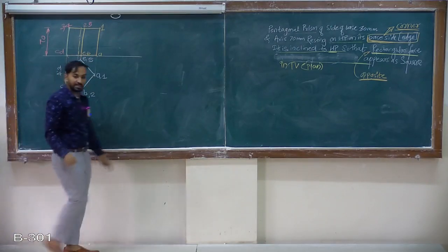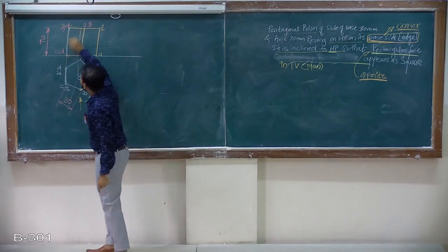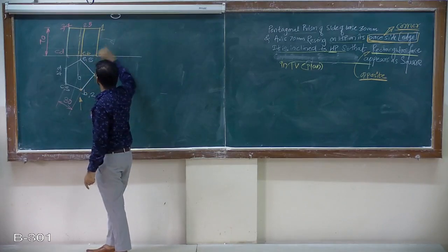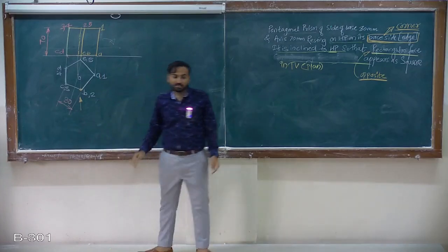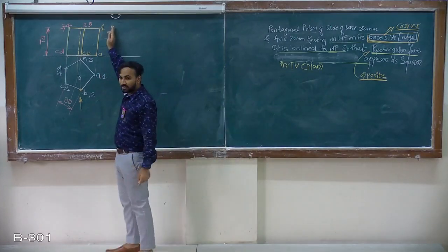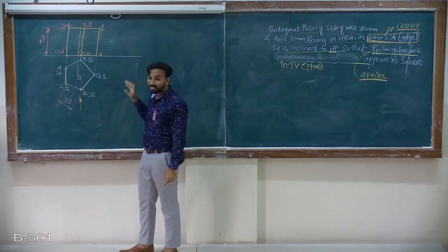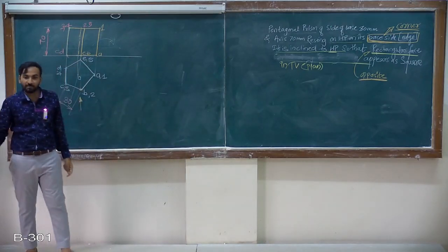Now CD 3 4 will be a square in the top view. So for this problem, I don't know the position of C and 3 4, CD or 3 4 after inclination, right? So both the points will be above HP. It is not the case like the previous problem when the resting side was a square. So I had drawn a square here, I had projected on XY, but this is not the case.